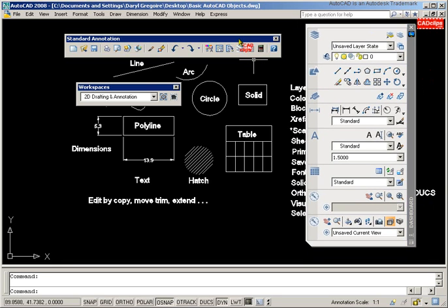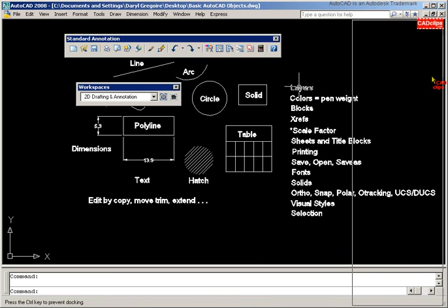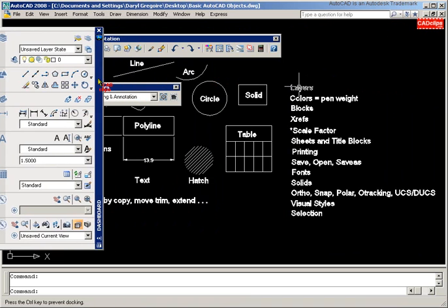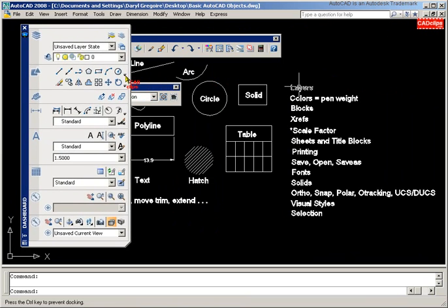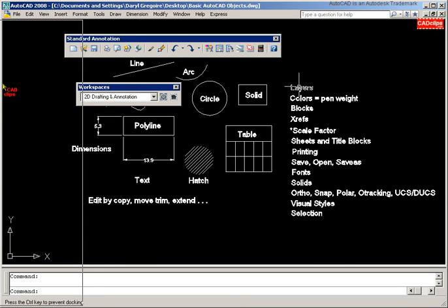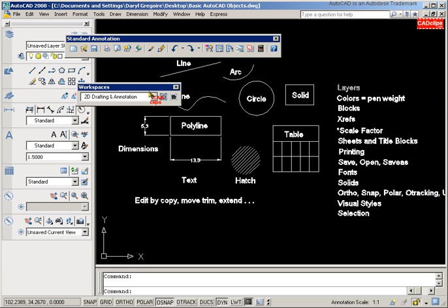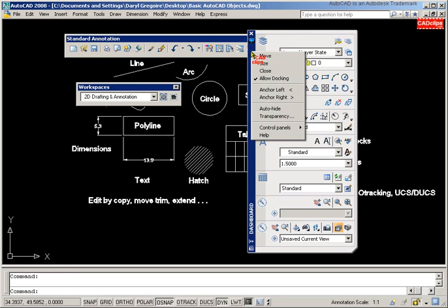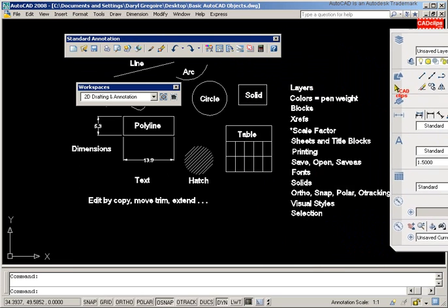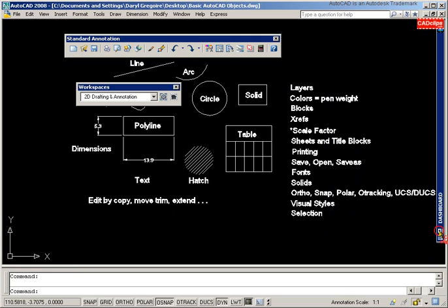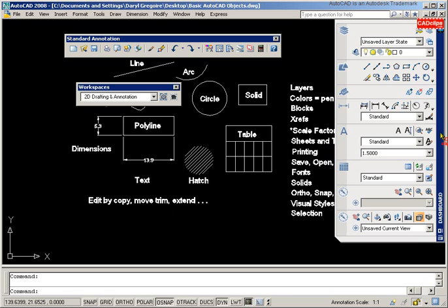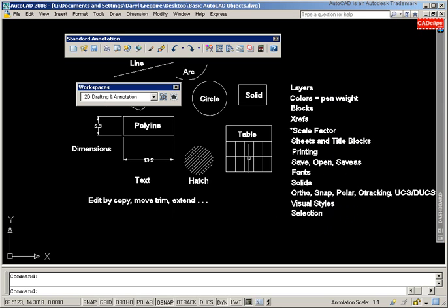Dashboards and toolbars are dockable. If you go near an edge, it'll start to kind of morph itself into that edge. If I go over here, if I go far enough, it'll flip it around. So the band goes on the left, and if you move it around enough, you'll notice that it will morph itself into there. And you can allow and disallow that. If you right click on here, you can say allow docking or don't allow docking. If you take this off, it's not going to dock itself in there at all. It's just going to sit like that, and then you can turn your flyout on or off. When you hover over it, it flies out, and when you move away, it disappears.